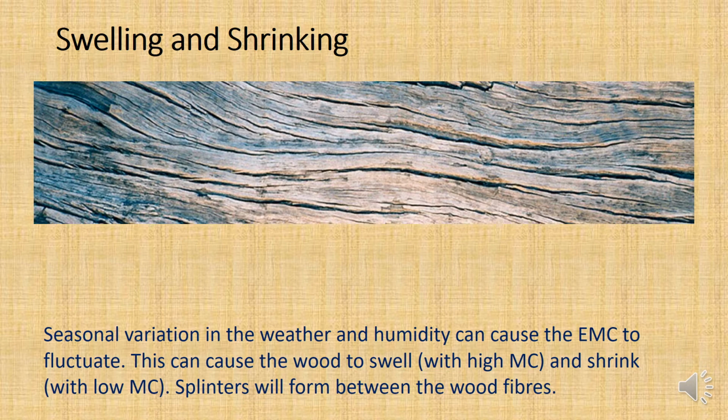So look at that picture of the wood there. Is that a good piece of quality wood? No, it isn't. That's actually quite old. We would say that's old wood, and it's got all of these cracks inside it. What's caused that cracking? Well, it's the swelling and shrinking of the wood going from high moisture content to low moisture content. What's causing that variation? Well, it's the weather. If you have a very rainy day and then a very dry day, a very rainy day, a very dry day, you're going to get variation in the moisture content,